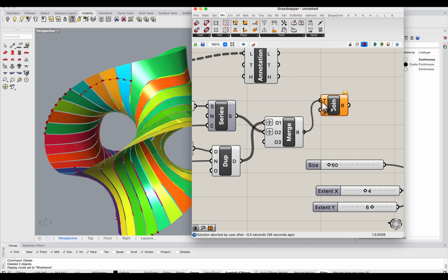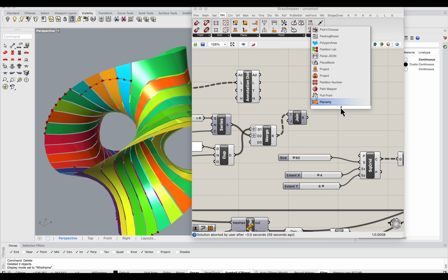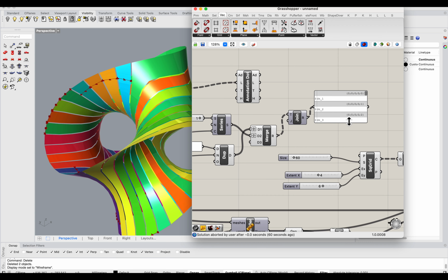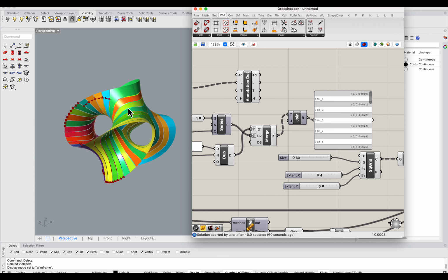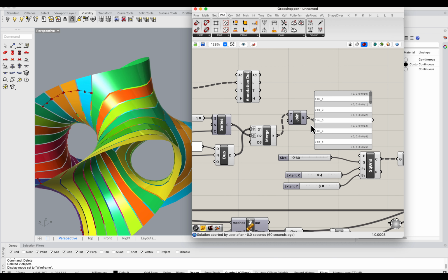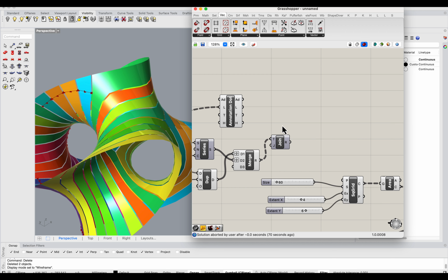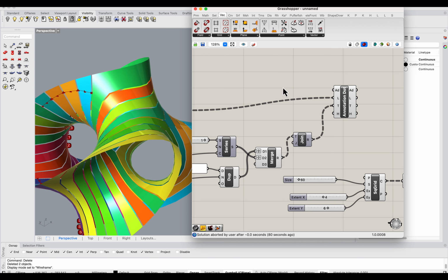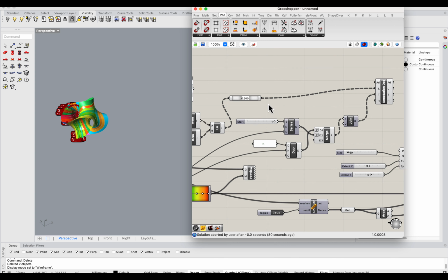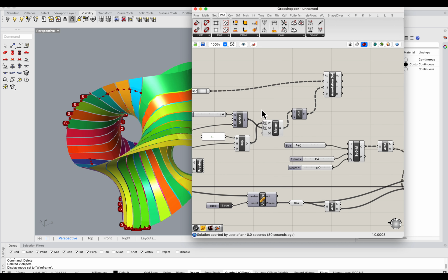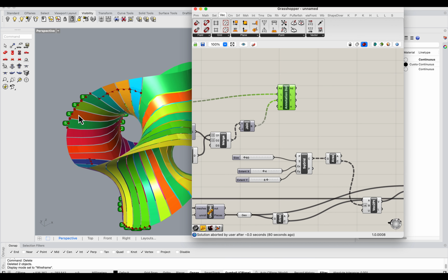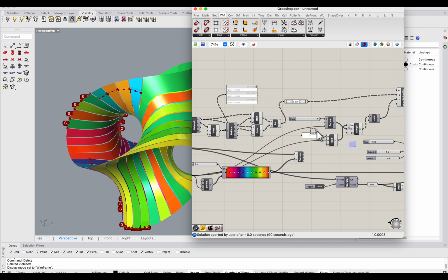Okay, and then we want to graft both of these, so they're put in clusters, and when you do text join, that will basically give you an ID tag for each individual strip. Depending on how you want to manufacture this, you might have different types of IDs, like different types of lettering. For instance, this could be just S. And we can then place these as annotation tags on the geometry. So now you would basically have a tag for each individual piece as well.